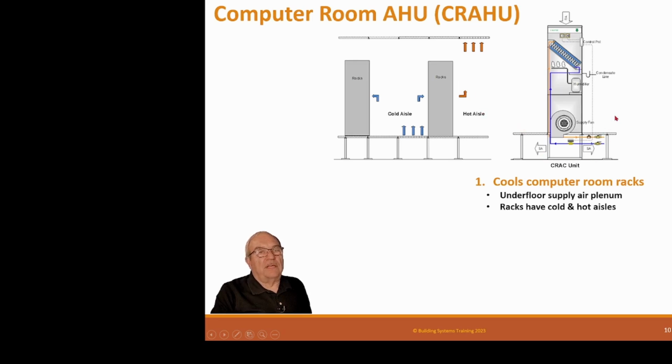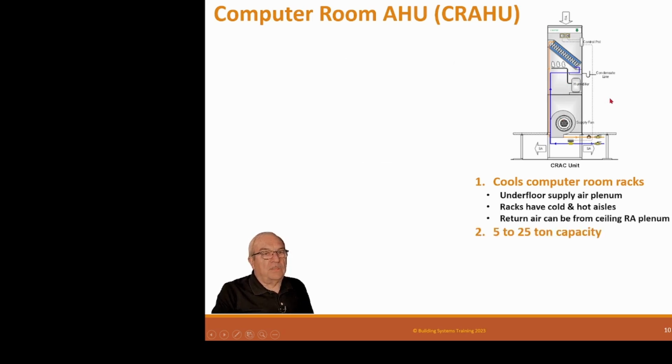The unit has a control system, of course, and the control system here is integral to the air handler. It is not provided by a third party. Like this job may have Johnson Controls, this will not be Johnson Controls. This will be proprietary controls of whatever the system is. So if you've got a Liebert unit in there, it's going to have Liebert controls inside of it. And all that the control system does, if you put a control system in here, is monitor what it's doing, because the controls are self-contained, and provide set points: what room temperature and room humidity do you want?